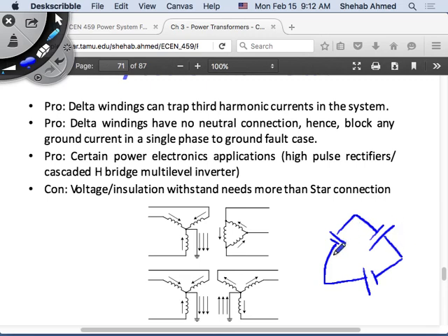Right? These are 3 DC sources that are in phase. The voltage polarity is the same. So these 3 DC sources, if you do KVL inside this loop, the sum of the voltages will be all 3 together. And you have an impedance of 0 in this loop, so you have an infinite current in this loop, basically.